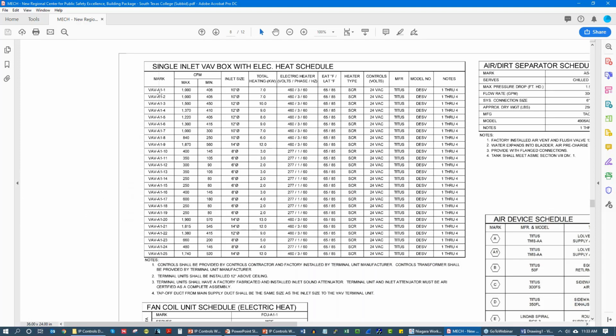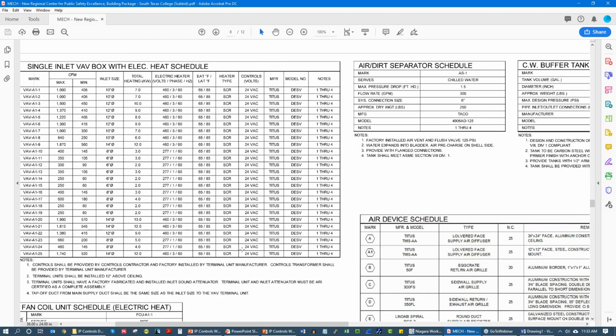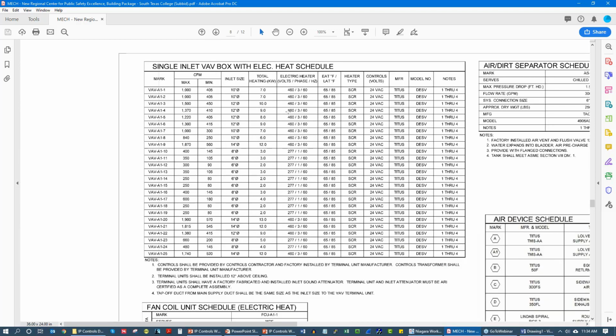Right off the bat, we can figure that we want to use our bus pattern most likely for our VAV boxes. Now, you may be saying, Phil, when do we decide if we want to use bus pattern or ring pattern? It's really a tolerance of failure discussion because technically we're in the design constraints for either pattern. We could do a bus pattern and we're 25 devices, so we're fine. Or we could do a ring pattern. We're under 40, so we could do that as well. It really just depends on our tolerance for failure.